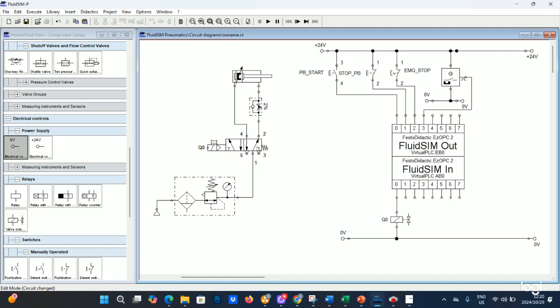Anyway, moving on. As I was saying, when you're using the spring-loaded 5-way solenoid, it's not retracting as a result of detecting the front end position of the sensor. So it has no way of detecting the front end position by the sensor, and it is not able to advance to the front end position without us latching the signal.